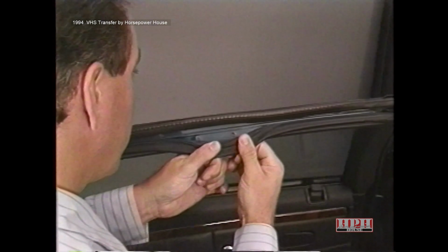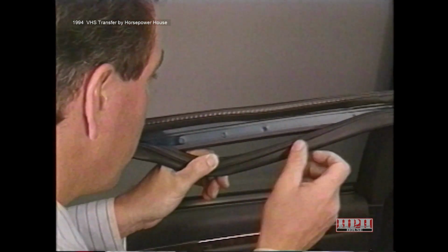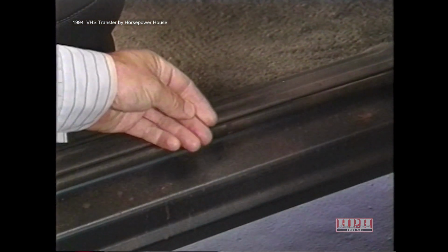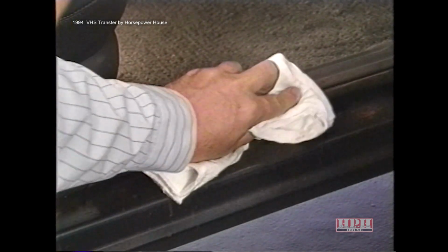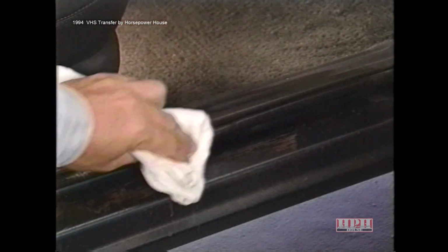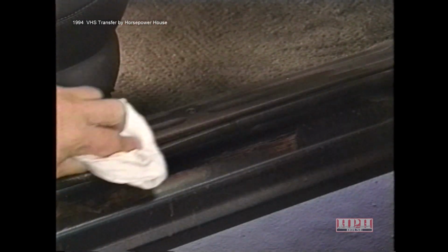Also, look for low spots or solder lumps on the door opening surfaces, which may prevent proper weather strip contact. And if you notice any especially dirty seals, you should wipe them off and inspect the area carefully for gaps or tears, since dirt and grime can cause excessive wear to the seals and weather strips.